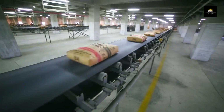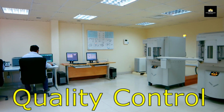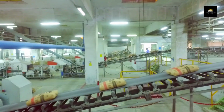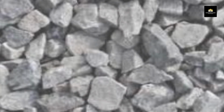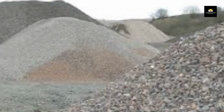Since cement is a vital ingredient in concrete, quality control at cement plants is rigorous. Laboratories frequently conduct chemical and physical tests to ensure each batch meets industry standards. Once the cement is ready, the next key ingredient is aggregate, which makes up as much as 75% of the volume of concrete. Aggregate includes both gravel, coarse aggregate, and sand, fine aggregate.